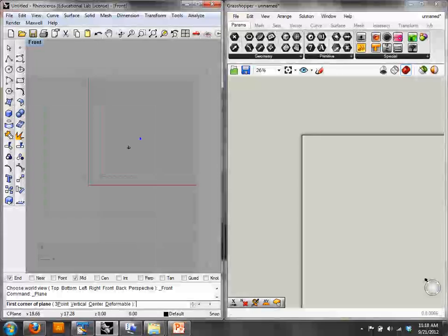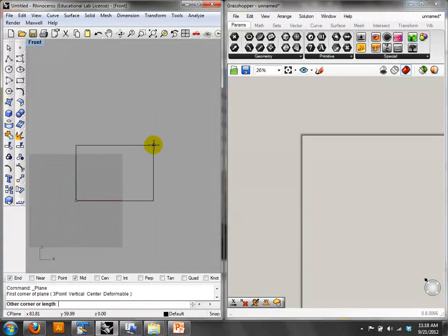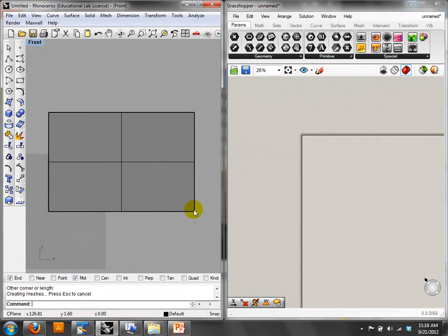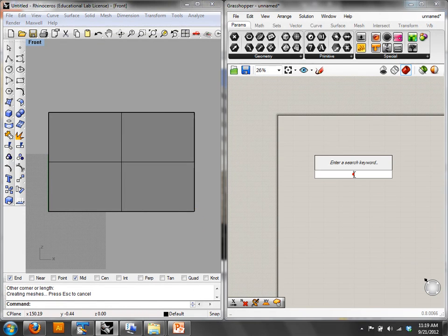So first thing I'm going to do is start with a reference surface once again. So make something. And you want to make these things fairly large when you do them. It's easy, because there's no scale inside Rhino, to just make something that you think is a pretty decent size, but it turns out that it's only like a foot across, and then all your sliders have to be minuscule for it to work. Okay. If you can, trace the drawings that you have and get it to be roughly the size of that wall that you're working with, that's really helpful. Because then you can use the drawings that they give you to figure out what the sizes of those panels or of those windows are. Okay, I think that's helpful.